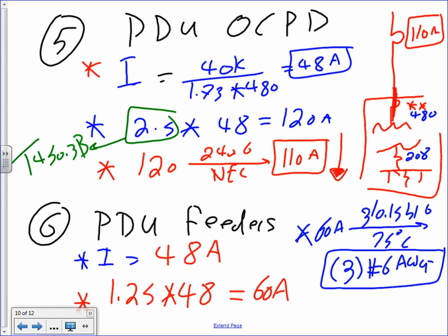In our project, guys, just for the ease, we give you 1 UPS with 1 PDU. But we want the 2 PDUs to be the same size. So if one of them is to crap on you, you just shift the load. You don't have to, because your servers are plugged into both of them. So if that PDU is shut down, your server continues to run.